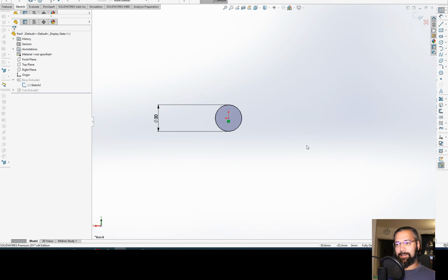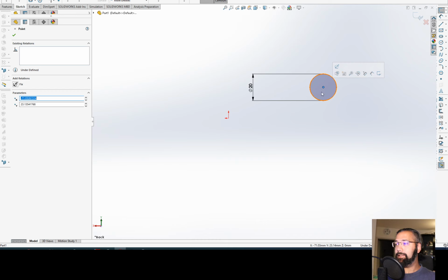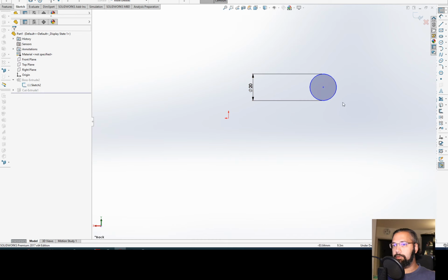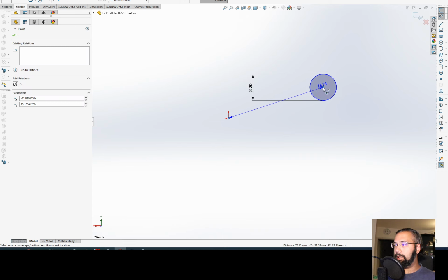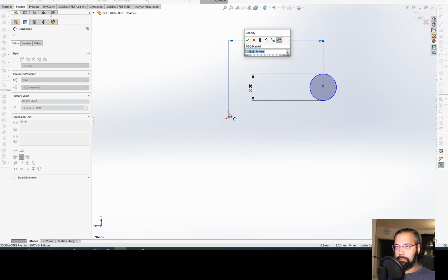And that's not to say you're not allowed to make volumes with underdefined sketches, but just get used to fully defining sketches and everything will be super easy. Or at least it will not be excessively hard. Now, another option, basically you need some kind of relation to the origin, either by telling the center of this, specifically it's the circle, rectangles behave differently and so on.